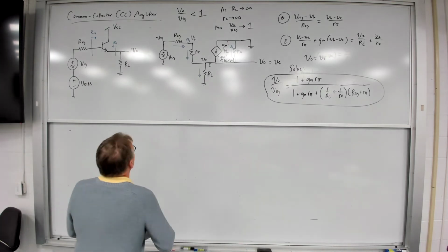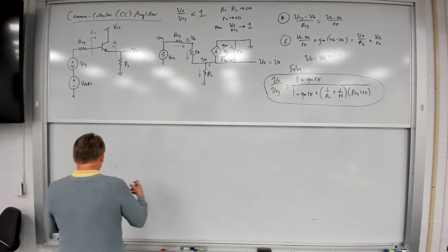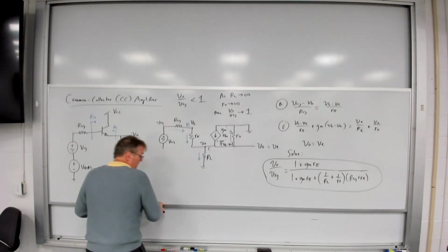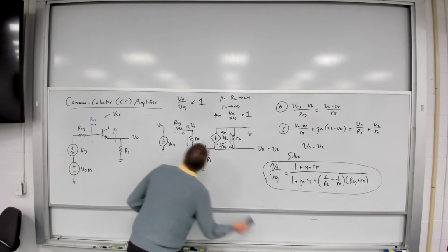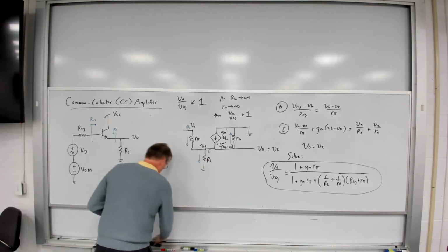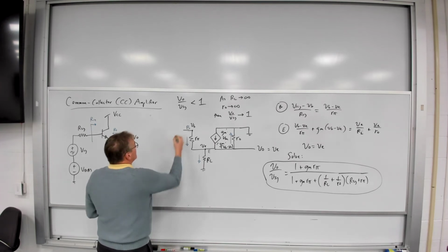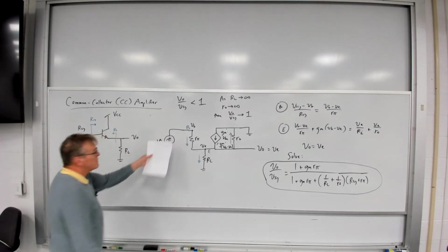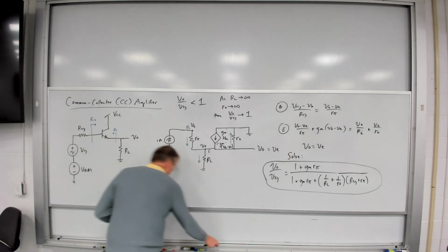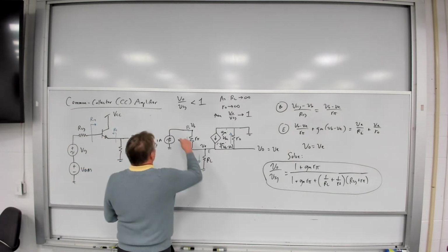So if we look at our Rn for our amplifier, let's go back up here real quickly. In this case, I'm just going to remove the source, do a 1 amp into the input, source driving into the base so that I can derive my Rn value.